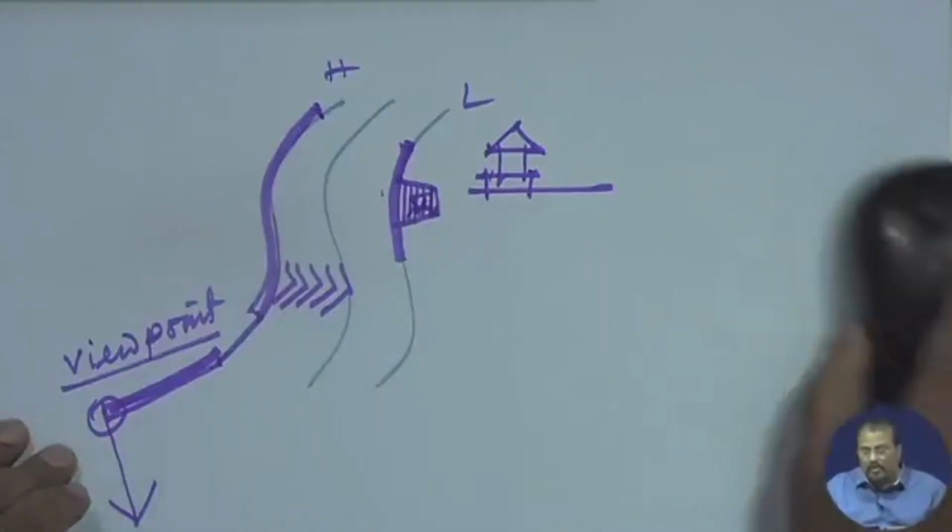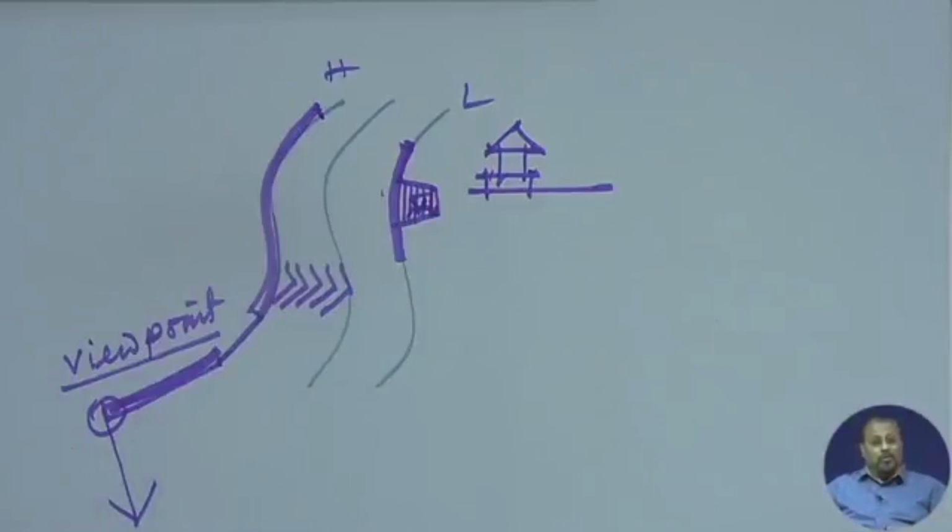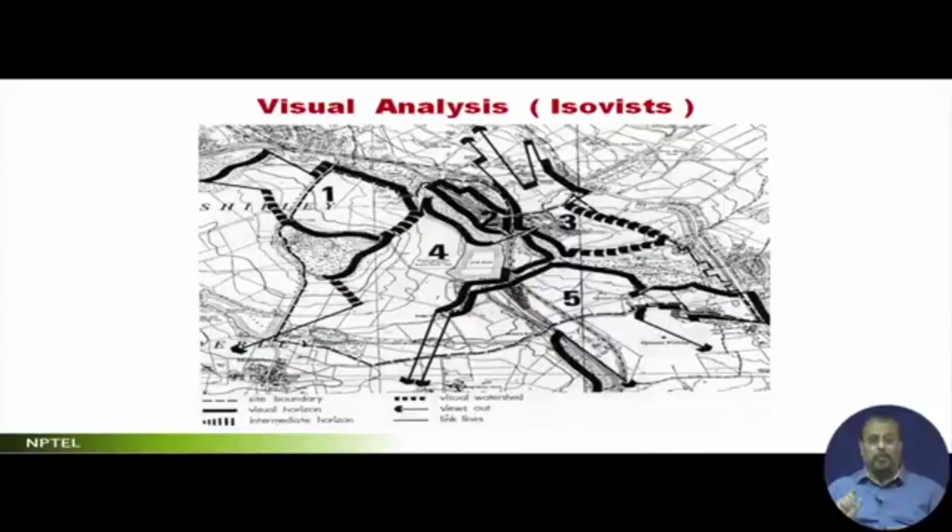This is visual analysis. In fact, you will find when you do the reconnaissance survey, your visual analysis generates at that time only, and you start recording all these things. And the last thing that will now remain in this analysis is the laws and regulations. If you follow all these analyses one after another, how do you collate? Each analysis is independent with respect to the different functions. Now you superimpose all these one after another, and whichever function you find has satisfied the maximum number of analytical positions in this analysis, that earns the point, and that is the point at which its location gets fixed.